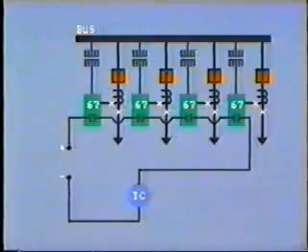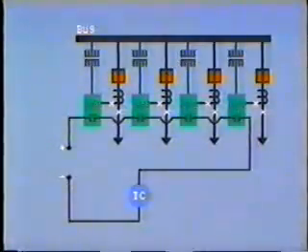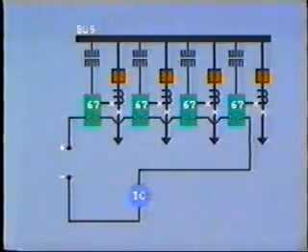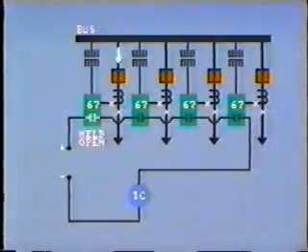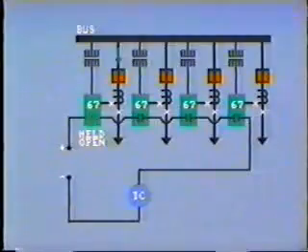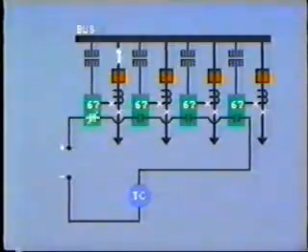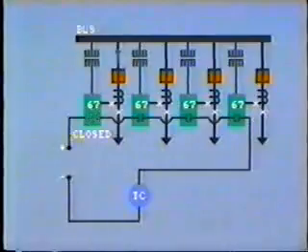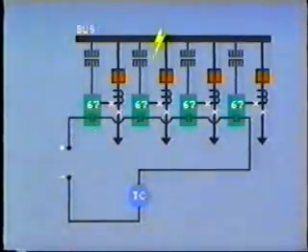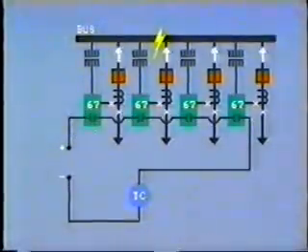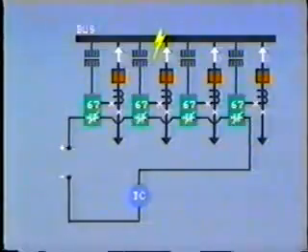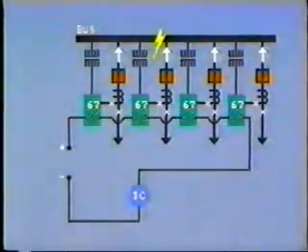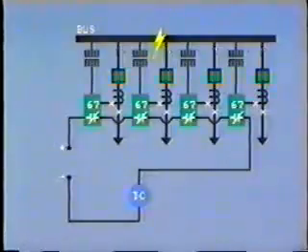One improved method uses directional relays fitted to every circuit connected to the bus. The operating contacts from the relays are all connected in series. When current flow is out of the bus, its respective relay contact is held open. Conversely, when current flow is into the bus, the contact is closed. For a bus fault, current will flow into the bus from all circuits, and consequently, all of the contacts will be closed, energizing the relay to trip all of the breakers.